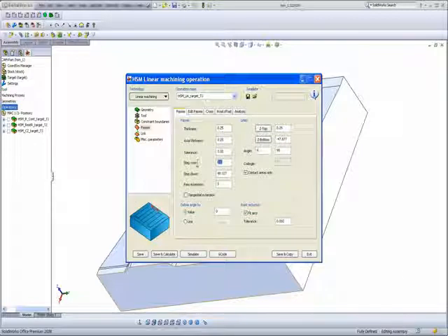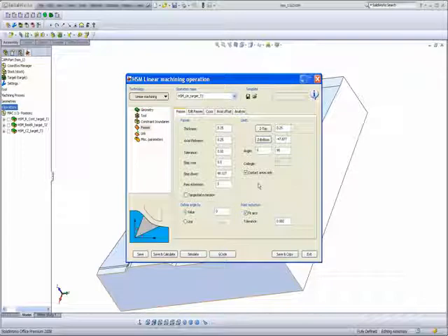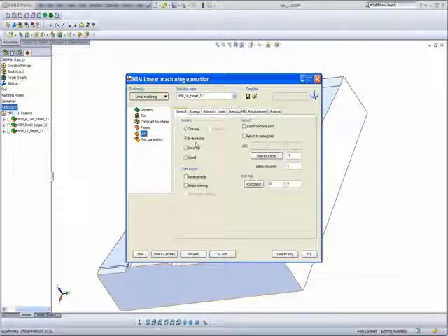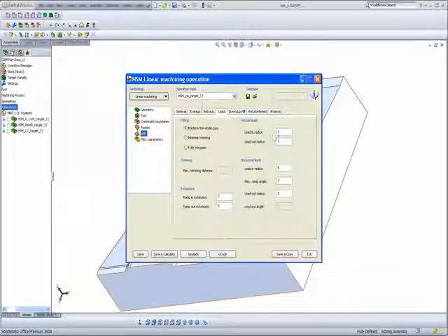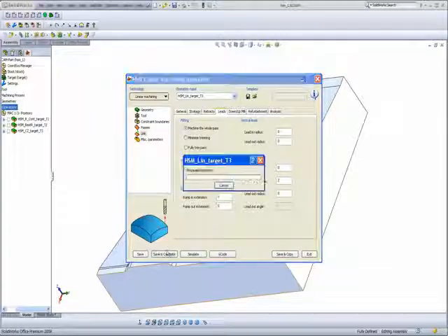And a step over this time of 0.5. But this time, I'll limit my angles from 0 to 42, giving it 2 degrees of overlap between the machining options. In my link area, again, I'll be going bidirectional. And in my leads, again, I'll change this to 0. And as we see after we calculate, we're able to see the simulation.